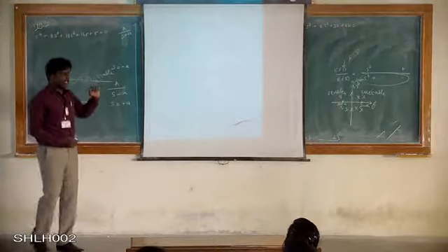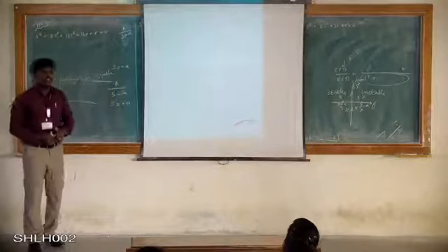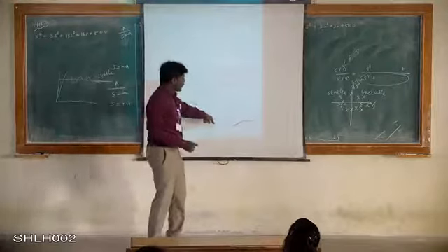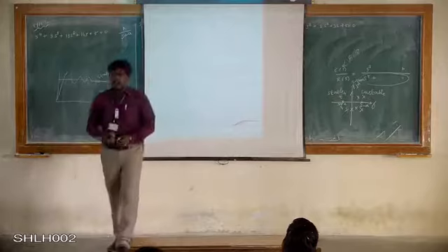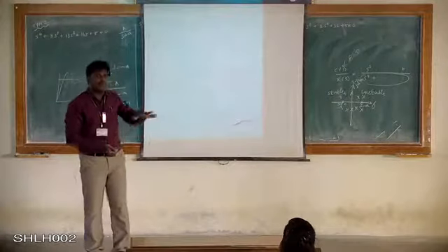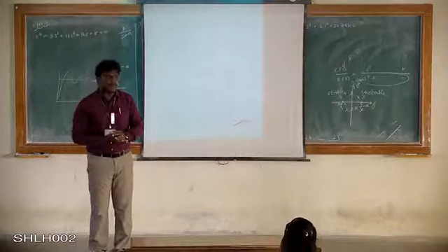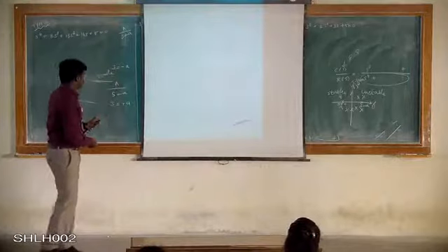The system will be stable. Here your system is A divided by S minus A, your root is S is equal to plus A. For that, your output will not be stable, right? So, the system will be unstable. For various inputs, how your output is going to react is also given in this PPT. We will also be discussing it in tomorrow's class, right?